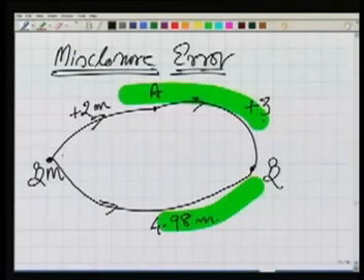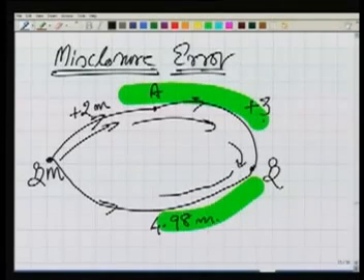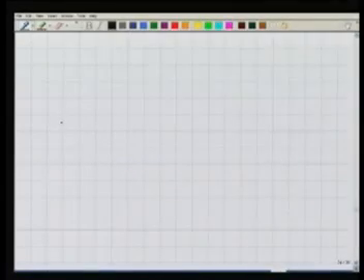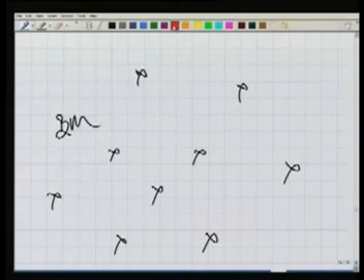Generally when we do the leveling, we start from a benchmark and go to various stations. Let's say we reach A, we reach B, and from B we finally close at the benchmark. If I draw it again, in any leveling, the benchmark is here, and there are various points for which I need to find the RLs.